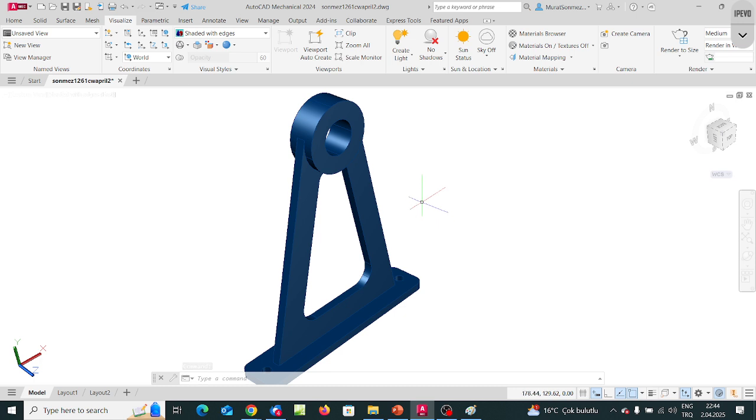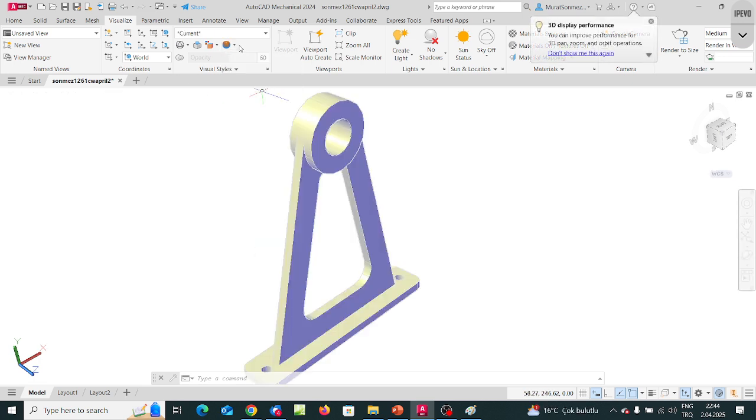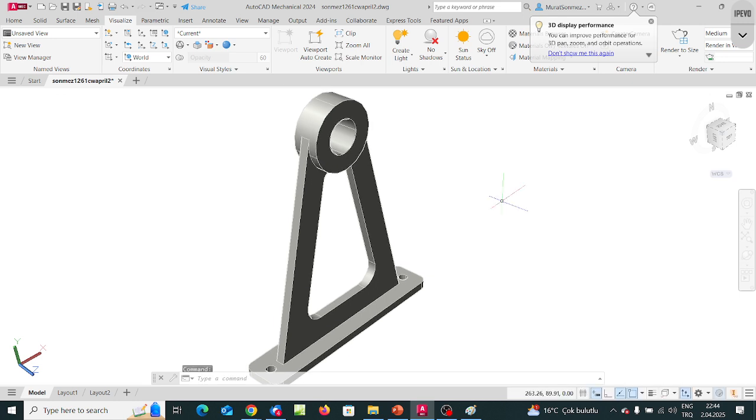For the object layer, the selected color is dark blue. But you know the trick. In the Visual Styles panel, drop this list. First select Warm Cool Face Style, and then Realistic Face Style. Then yes, now see the model in the color of steel.